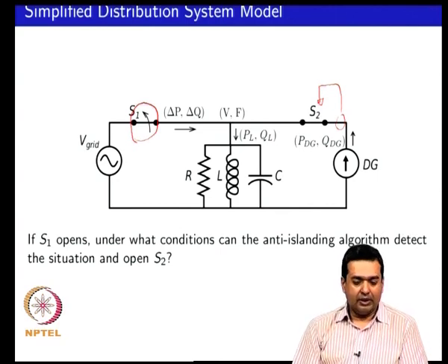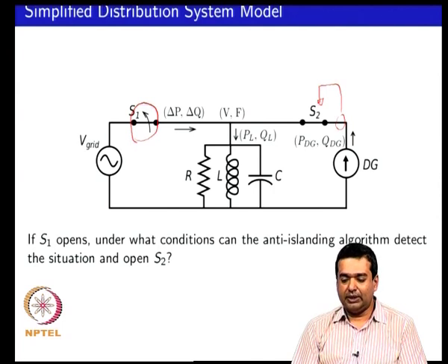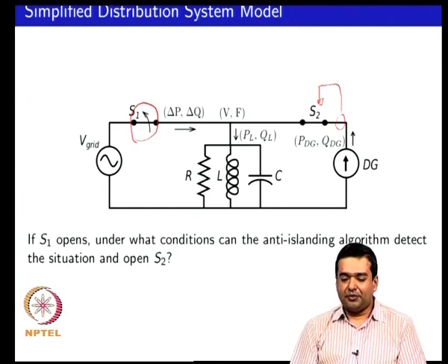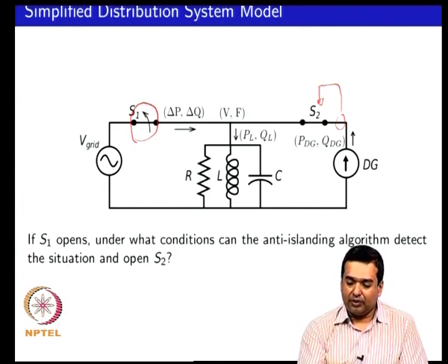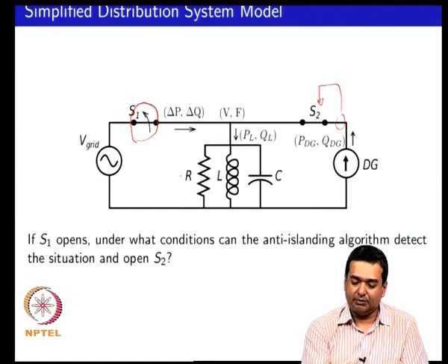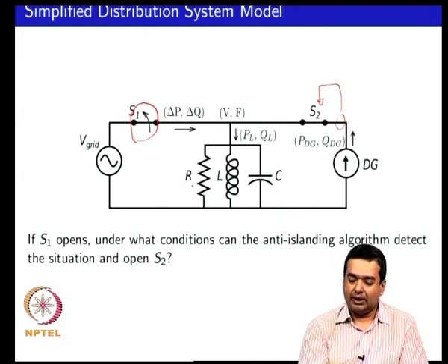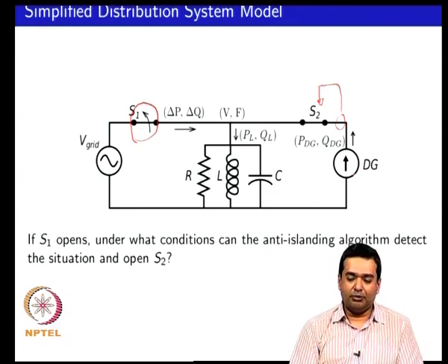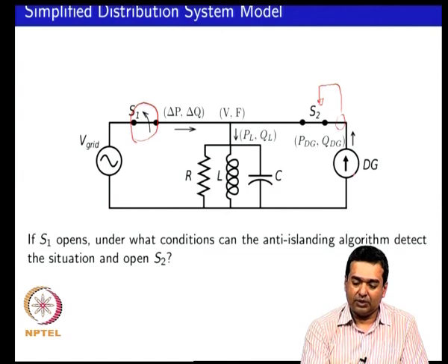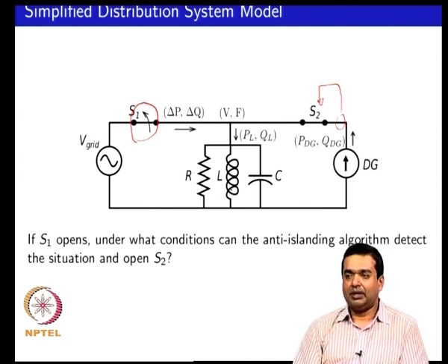And so, then to analyze the situation, we defined what the problem should be under nominal conditions. If you have a situation where the power that is injected by the DG exactly matches the real power consumed by the feeder, and if the injected reactive power of the DG is 0, so essentially the DG is operating at unity power factor, and if whatever reactive power is drawn by the loads on the feeder is exactly compensated, that would correspond to a situation of an RLC circuit which is at resonance at 50 hertz.